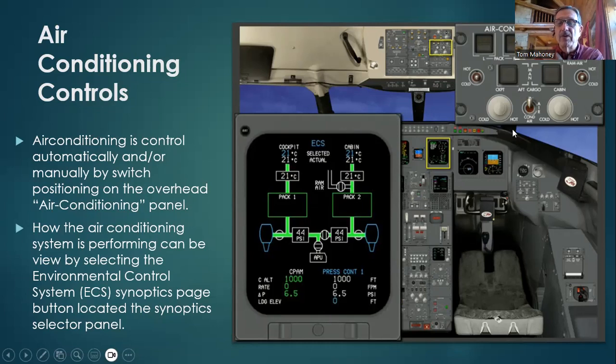the selected temperature. So we would use, for example, here for operating the cockpit side, we can operate it to the colder or hotter positions. If we select 21 degrees, we can turn this knob till we see 21. Then the temperature will gradually increase or decrease to try to match up and have these two temperatures match.